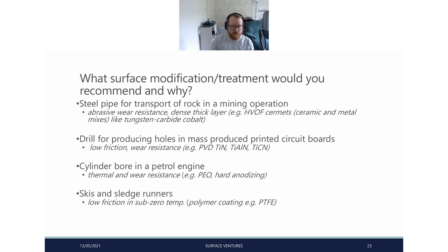But moving back onto this, so PVD, perfect for drills. So this is the sort of thing we're looking at. Ceramic coatings. So if you've ever seen any gold drill bits, those would be your titanium nitride, titanium aluminum nitride, titanium carbonitride, all of these giving good hardness up to a high temperature, good wear resistance. So basically allowing our tool to remain in action for as long as possible and keeping the geometry there.